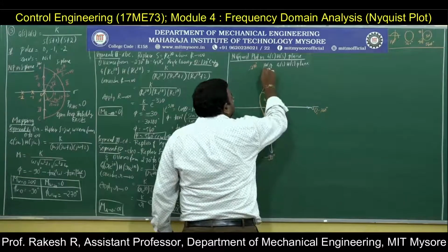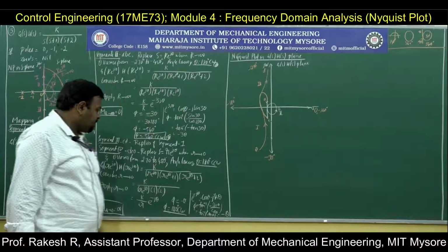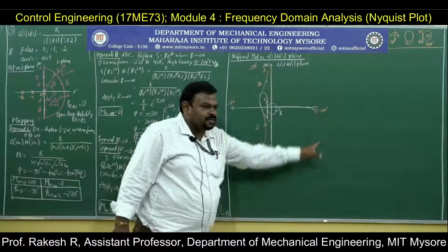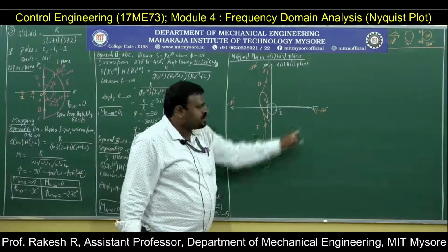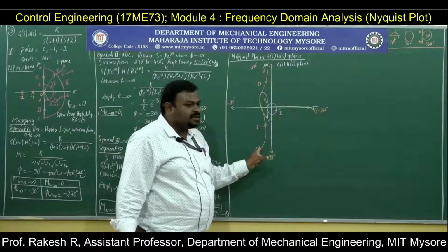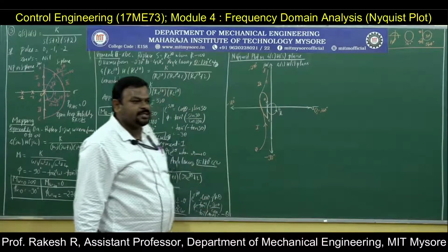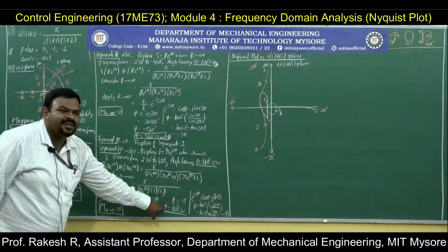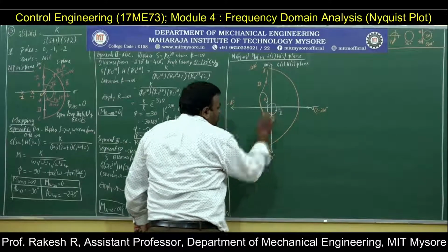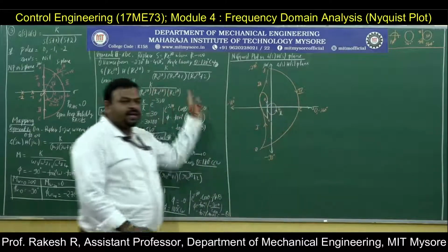This is segment 3, CD. What is the segment 4? Segment 4 is magnitude infinity. Magnitude infinity means you are at infinity here. So this is infinity. And see this, you want to close this. Always you will get a closed plot. Here, if you close this, the direction of the plot is clockwise direction. The angle coverage is 2 quadrants. 2 quadrants means 180 degree. Is it correct? Yes, 180 degree clockwise. So this is the closing plot. This is segment 4, DEO. 180 degree clockwise.